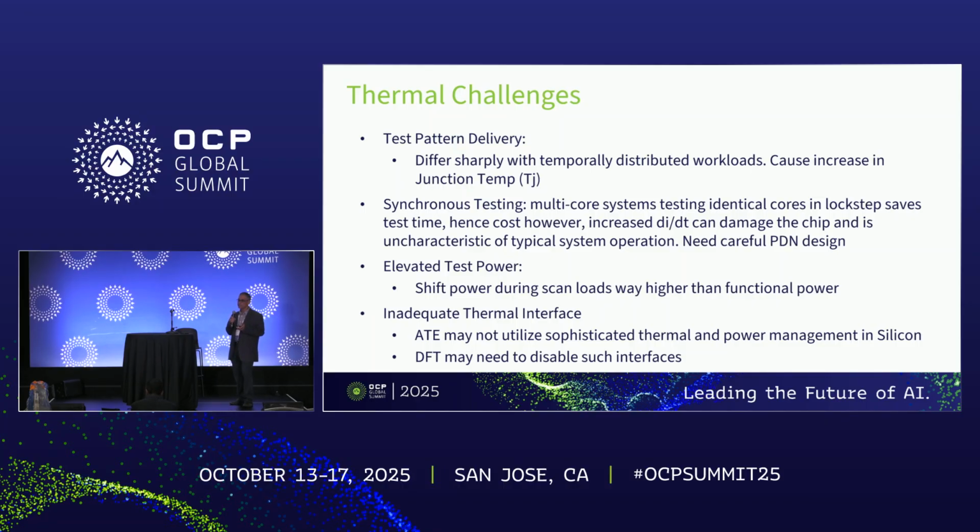And also the physical design team needs to understand that the PDN, the power distribution network, is basically addressing these issues. And then ATE definitely has its own limitation: although there are functionally a lot of power throttling features, you don't exercise that on ATE.